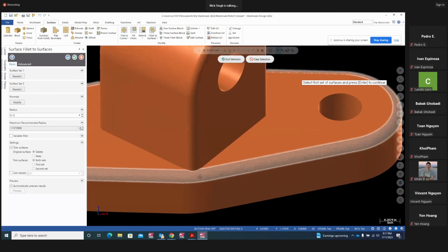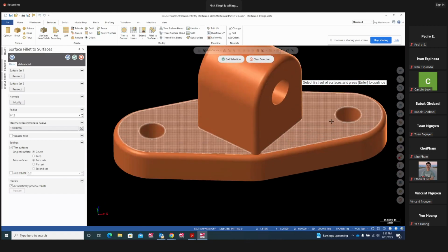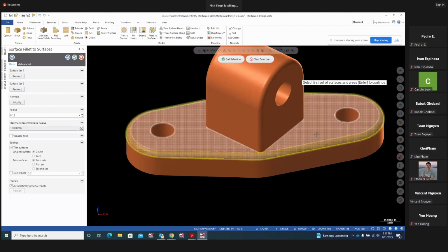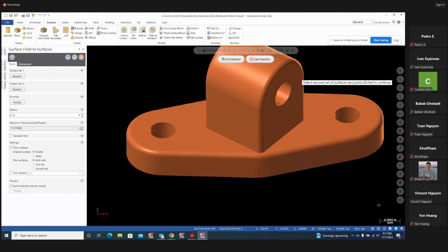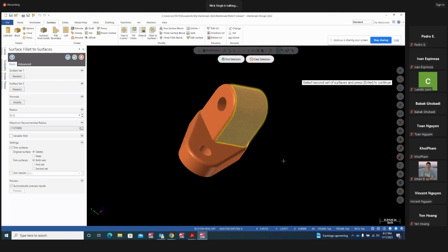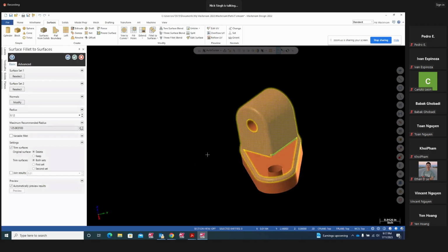Now the last fillet is going to be on the base. This is what I was telling you, because this has to blend with this here, so we have to have these fillets first. So first set, again, is going to be this here and this here. That's your one set. Hit enter. Second set, 1, 2, 3, go revolve around, 4, and 5. That's your second set. And hit enter.